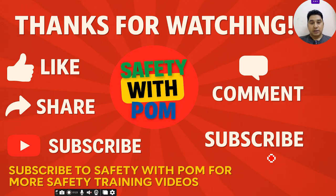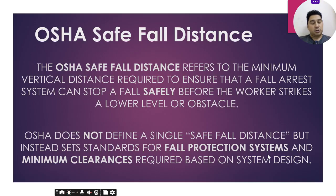So let's start the video about the safe fall distance as per the OSHA requirements. Before starting, to calculate the safe fall distance, we have to understand what the meaning of safe fall distance is. So let's go through this first. As per OSHA, safe fall distance refers to the minimum vertical distance required to ensure that a fall arrest system can stop a fall safely before the worker strikes a lower level or obstacle.